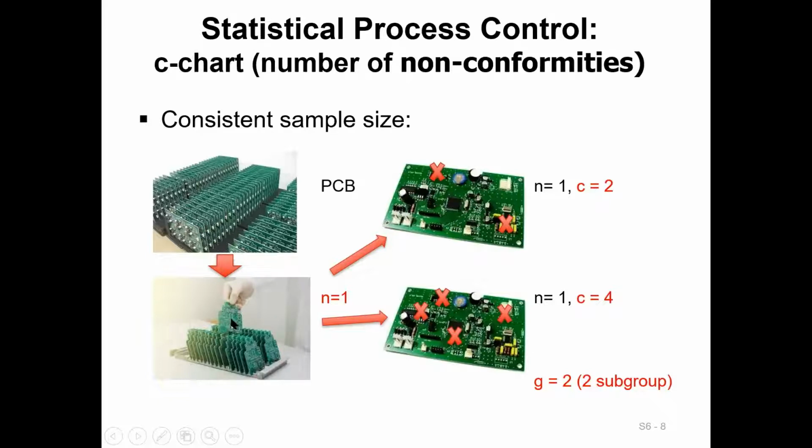the first criterion is that the sample size must be consistent. Every time my inspector is picking one sample. And in the first sample picked, for example, they detected there are two defects. Not defective items, there are two defects. For example, soldering uneven and IC alignment out. Okay, so C stands for the defect. C equal to 2, or C is the defect. NP is the defective item, C is the defect.